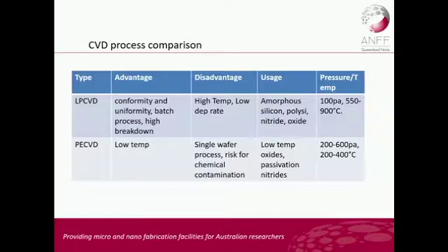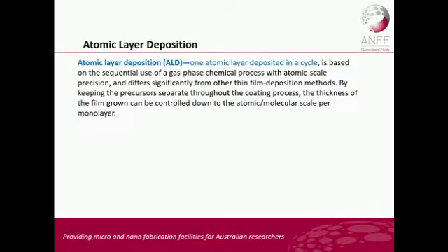Disadvantages: LPCVD uses high temperature and has low deposition rates. PECVD is usually a single wafer process, and the risk is chemical contamination. And this is a typical temperature we're using for PECVD and LPCVD processes.